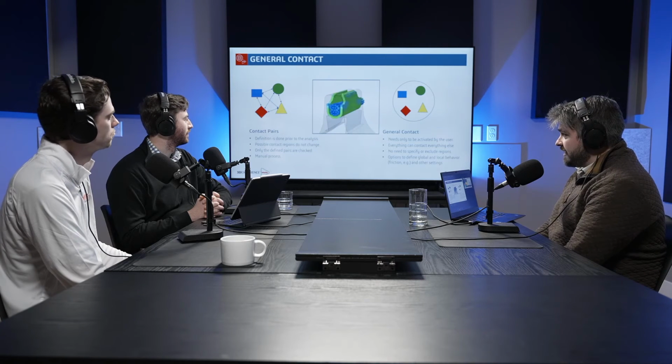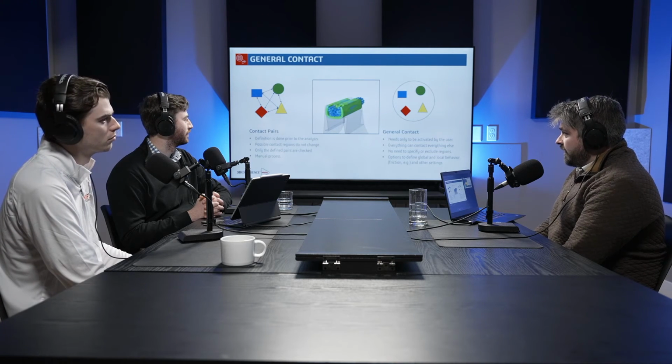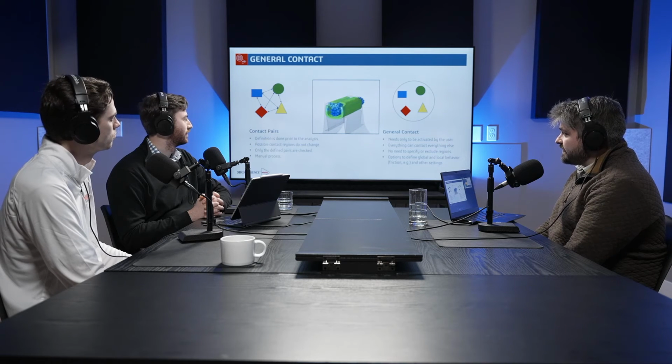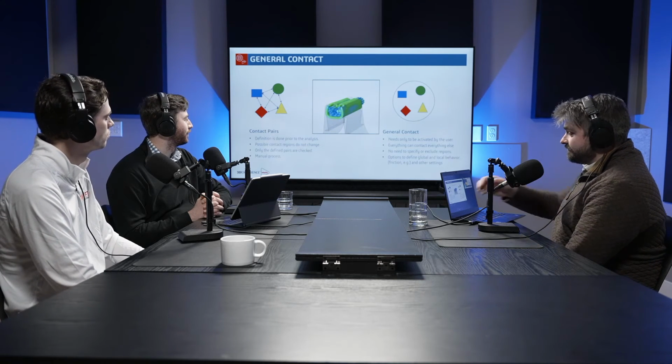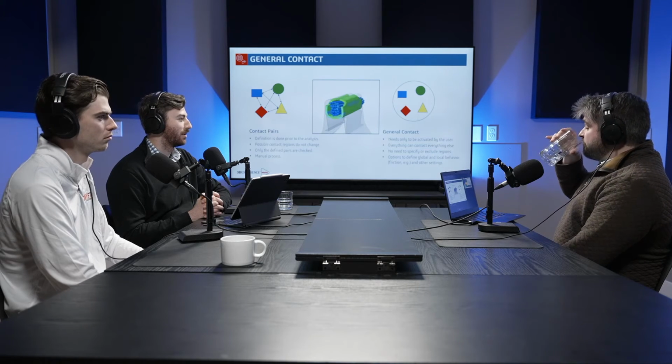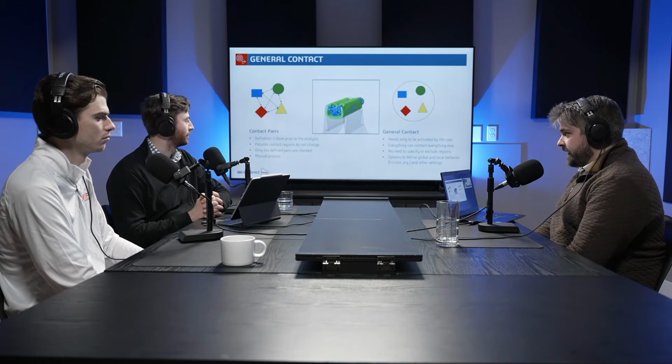I wasn't kidding. This is that same wire crimping example that I was talking about earlier. I can't say impossible to do in SOLIDWORKS Sim, but it is hard to do accurately. What about friction? Is that defined in the material that's applied to the part or the contact itself? It is applied in the contact and the material, actually. So you can do both. But that's sort of how this all gets set up.